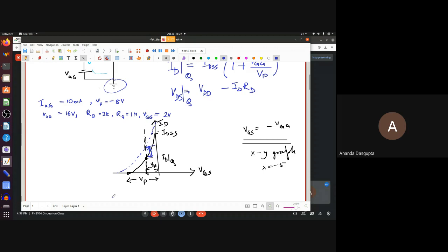Okay. So this is the same kind of issue that we saw with the BJT. In a BJT circuit, the easiest possible biasing circuit, the fixed bias circuit, is very, very simple, but doesn't really work very well because if there's a drift in temperature, or a drift in the parameters of the transistor because of aging, or because you have to change your transistor and hence beta changed, your bias point would change a lot.